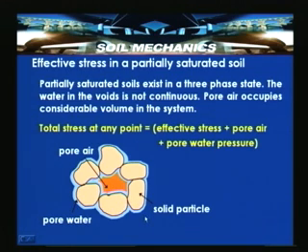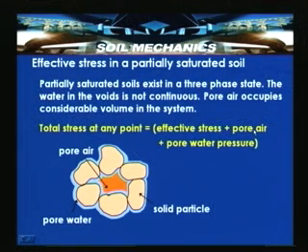So, in such situations we cannot say that the equation sigma dash is equal to sigma minus UW is valid. In those situations, total stress at any point is equal to effective stress plus pore air pressure plus pore water pressure. That is, total stress is equal to effective stress, which is mobilized in the form of interaction from the grains, plus pore air, when the air is under pressure, and pore water pressure.